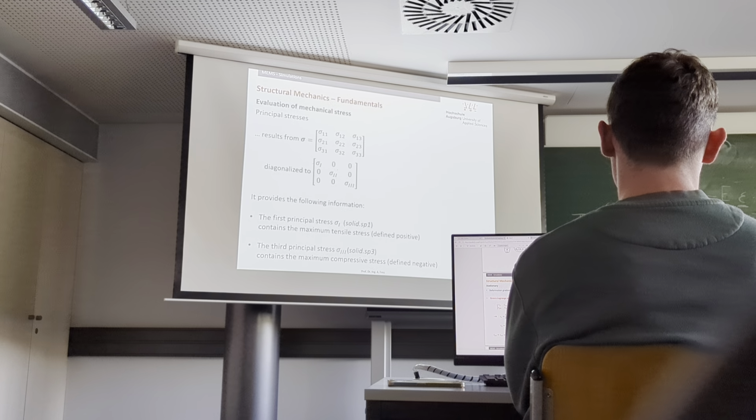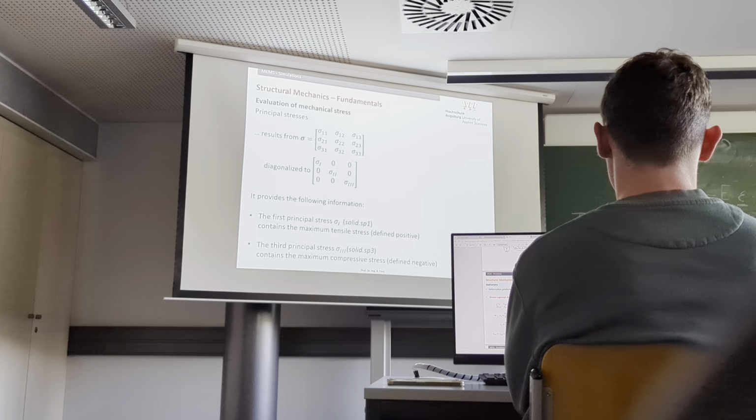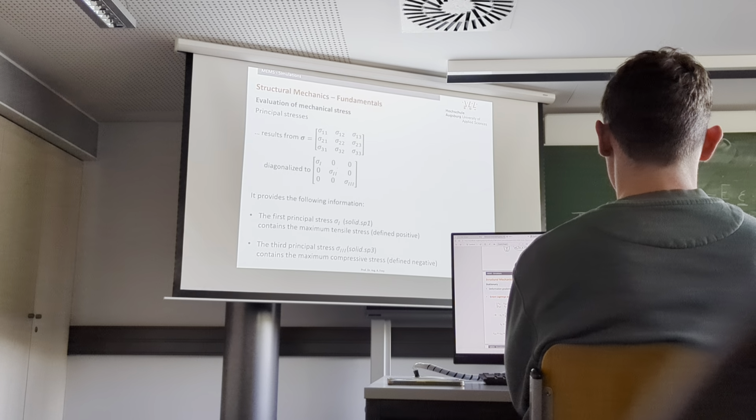So probably this is the more important thing. If you look for that third component, the point is just a practical thing. I mean, COMSOL can calculate this, but somehow you have to display what you do with the 3 times 3 matrix, how to make use of this. And for that reason, it's very good if you have just simple parameters like that third principal stress, which you can plot, and then you can find out where you have the maximum tension. And then, of course, you are interested in avoiding bursting the material.